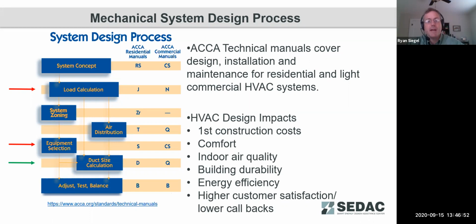Another contractor looked at it, ran through, did the design, and came back and said, no, for a building of this size and this design and this insulation, we're looking at just over 3.5 tons. So we're going to need a 4-ton unit. Just by that, the unit was able to downsize 20%. Plus, we're going to be able to have higher comfort and much better humidity control. Doing these little steps is very important.